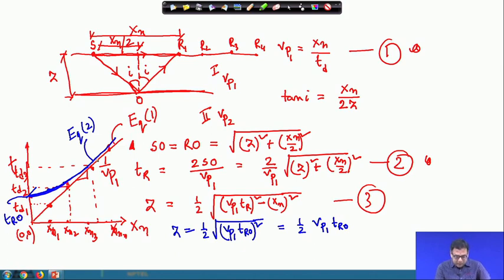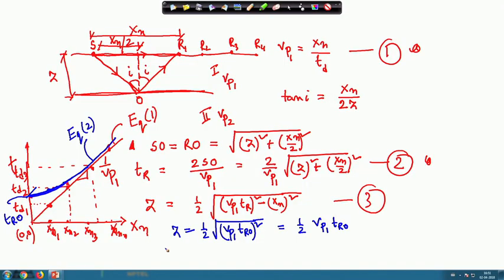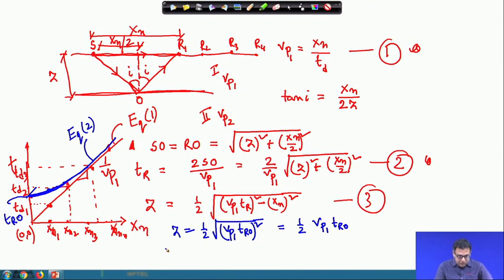To avoid that, we have to go for seismic refraction. In another way, even if we use this test, drawing a hyperbola graph is very difficult compared to drawing a straight line. So, instead of drawing a hyperbolic curve, if I draw a straight line, then it will be better. So, how can we do that? Instead of this curve, we have expression 2.